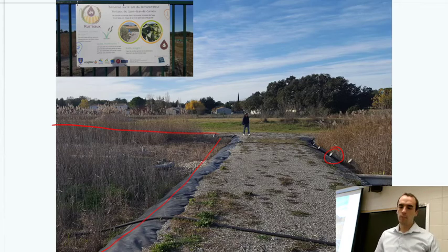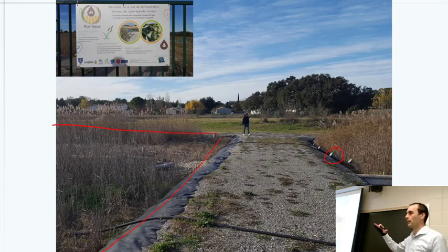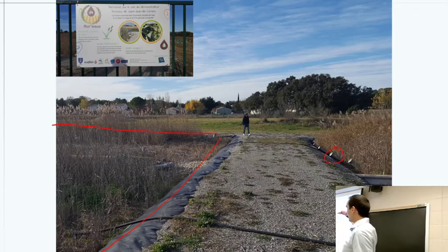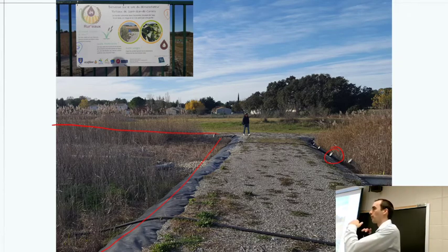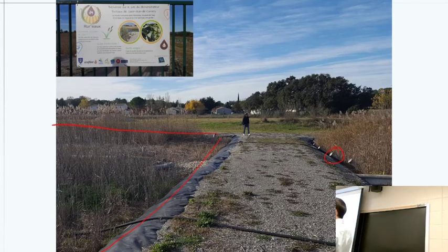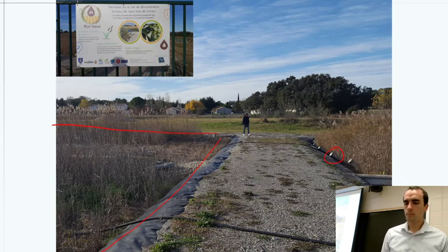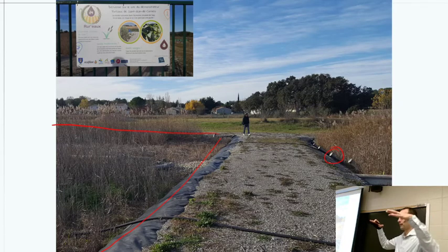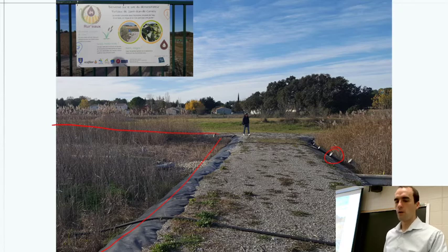I think sometimes they will drain these completely, and it may be sequentially, so that part of the time they have that water level up near the top, so maybe 6 inches, 10 inches away from the top of the gravel, and then they would drain it and essentially allow aeration by letting one drain and then fill back up. I think that was one of their processes. Maybe that was something they were testing. Okay, but this whole plot of land here contained, I think, 4 of these large wetland beds, in addition to a few kind of pilot scale stuff.